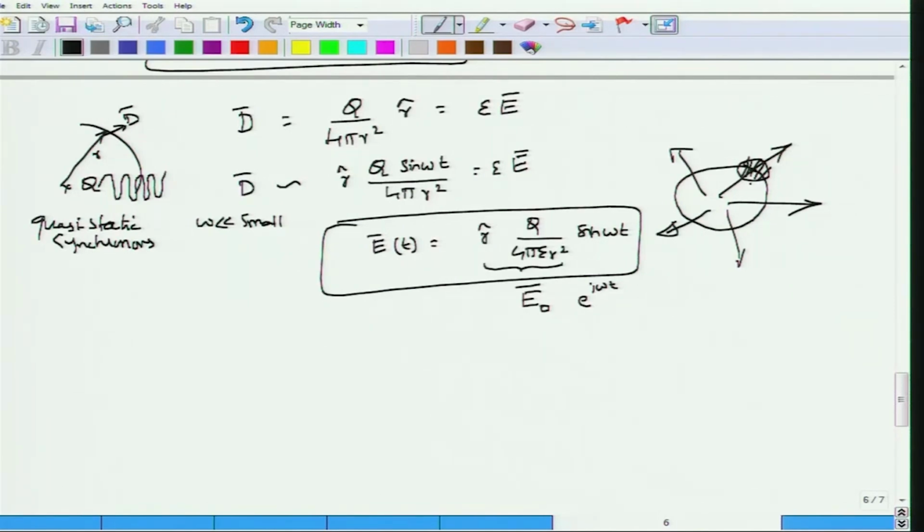So, because of that, you have this other equation, which is curl of electric field is equal to minus mu del H by del T, assuming that the material medium has a constant permeability mu. This seems to indicate that curl of E must be equal to minus mu del H by del T, but this must also be equal to 0, because the E field has no curl.